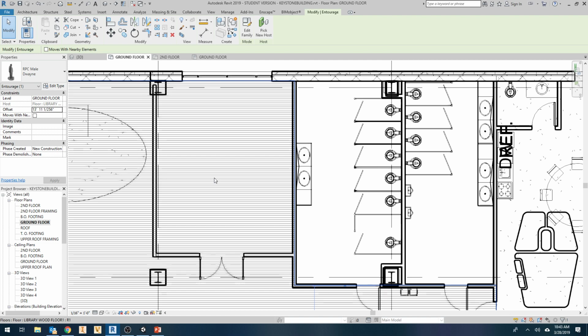So what I did was I put the stairs in, a 2-flight stairs like I just showed you with a landing on it. Put the hole in the ceiling, and then I put walls around it. I put your partition walls that we've been using, put those walls around it, and put double doors in like you see. Let me bring those stairs back.